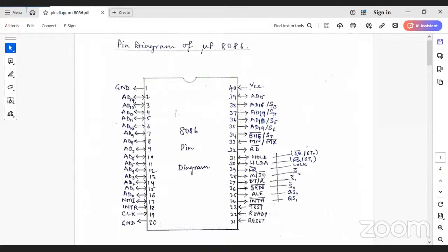So to use the bus also, there is a signal which is given. So that is grant bus access signal, that is given the notation GT. Now GT0, GT1, these are the two signals there. And then lock is bus priority lock control. So depending upon the priority, this particular bus is going to see.